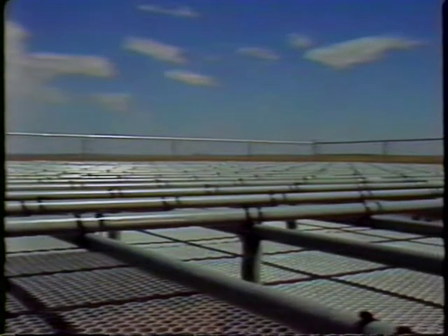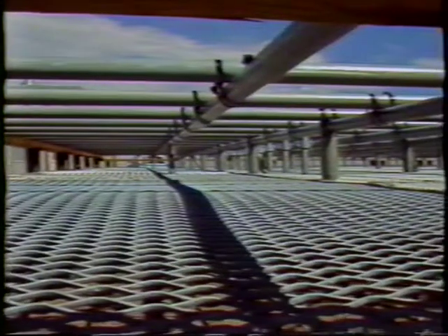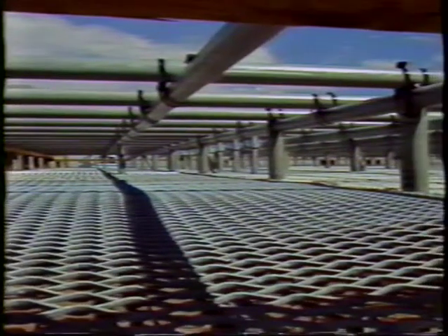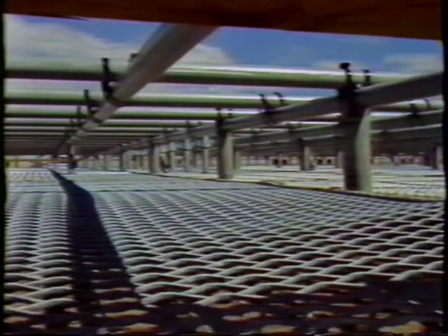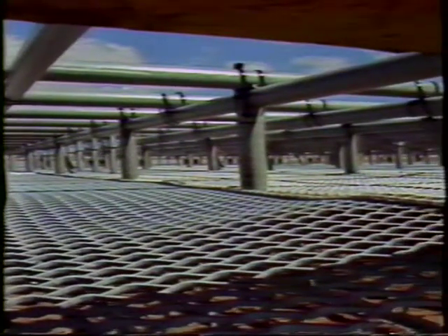In practice, the second antenna rests on top of the first one, forming a square array of cables. This causes no problems because only one antenna operates at a time. When the pulse is fed to rows of the second antenna and the phase is retarded from bottom to top, the beam points toward the north. In this view of the real antenna, fiberglass tubing covers all the cables to protect them from the weather, and black clamps hold the assembly together.